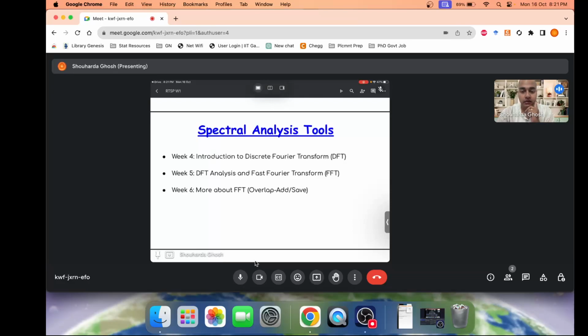And then we saw the computational complexity of the discrete Fourier transform. We observed that for an n-point DFT, the number of multiplications is of the order of O(n) square. So as you increase the value of n, the computational complexity rises by order of square.